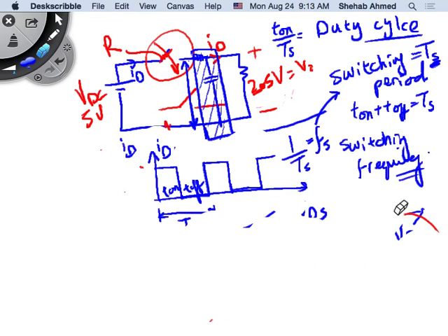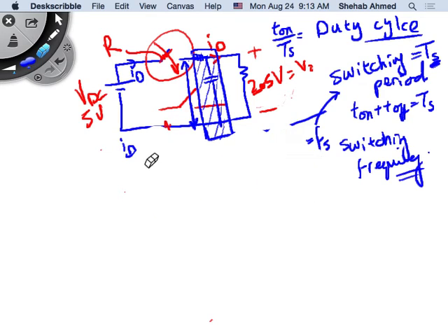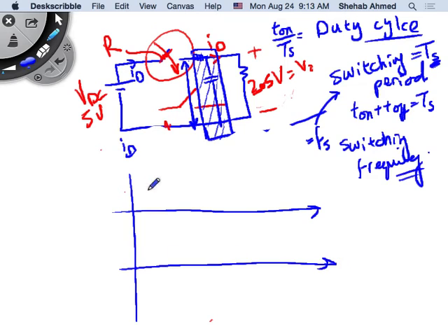What's happening to the voltage across the device? But is it in sync with the current or out of sync with the current? Out of phase with the current, right? So when the device is on, there's current going through the device, and then the device is off, there is zero current, theoretically speaking, right? And then on, off, right? And then voltage is doing exactly the opposite, because when the device is off, we said what?